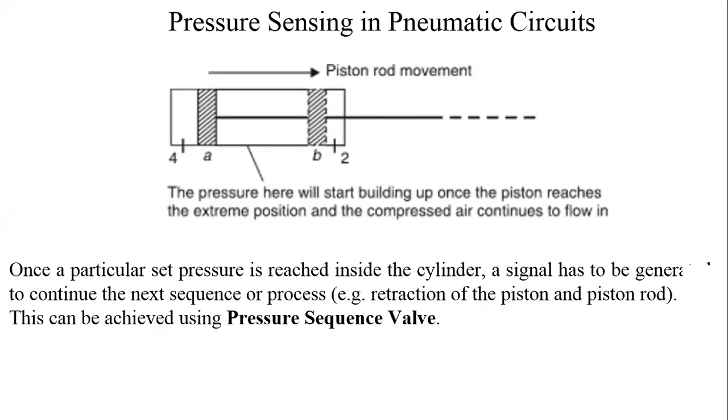up to final control valve. There are number of control valves in the system, but all the control valves are not final control valves. Some of the control valves are actuating or activating final control valves, and final control valve is serving the purpose of making the control air available to either of the sides of the cylinder, let it be full bore side or rod side of the double acting cylinder. So in the circuit diagram you can differentiate between signal air and control air. That is good thing. Now let us see